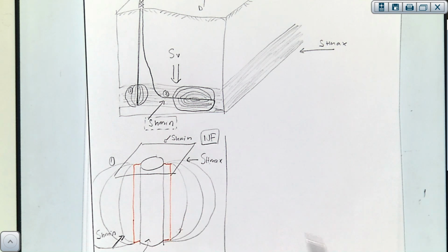If you remember from, I think it was the first project that we worked with, we looked at variation of stress with depth, and we looked for kind of a sweet spot where the hydraulic fracture would stay, because that was the local minimum of the horizontal stress. So it's going to depend on that, and usually they tend to grow up rather than to grow down. But again, it depends on the profile of stress and the properties of the rock.